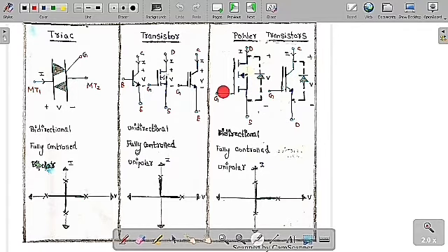Similarly, in the IGBT also there is an internal diode from emitter to collector. These are present inbuilt itself. So now we can say that current can flow in both directions, because in the reverse way the internal diode is going to help conduction. So this is called a bidirectional switch, and it is also a fully controlled switch, and it is unipolar. Means it can block only one type of polarity but not the reverse one. That is the reason it is called bidirectional, fully controlled and unipolar.